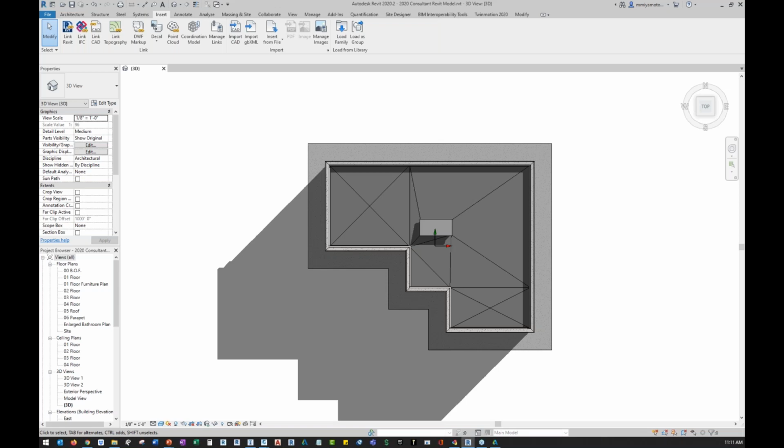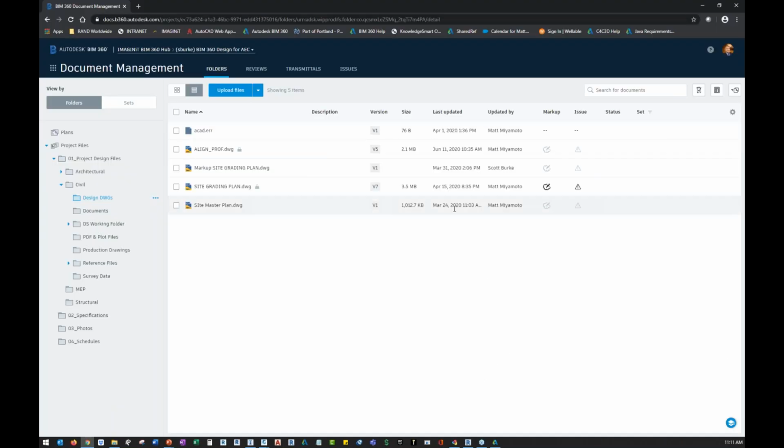So it's not instantaneous, and that's just something that we all have to learn to handle as we work in the cloud. You may see versions pop up there, but when you try to sync, it's not quite ready. Just give it a little bit of time, and when it's ready to sync, it'll sync correctly for you. You can monitor the actions through the desktop connector. And one of the things I try to do, not only check the version, I also look at the time on the last updated option, so that I can see if it's about the time that I was working on it.